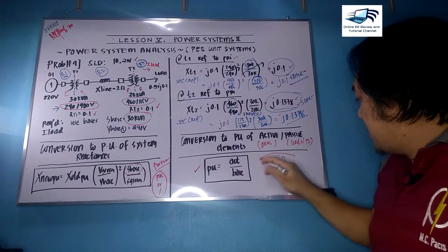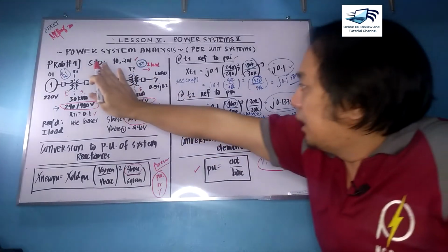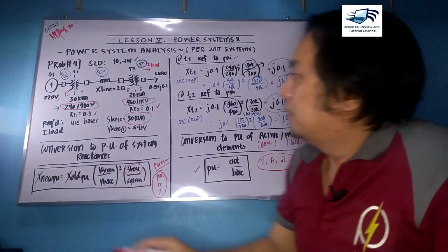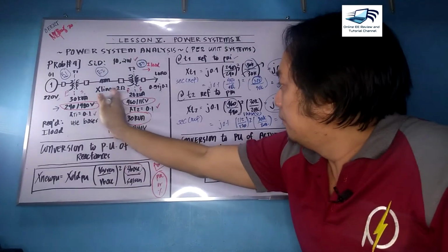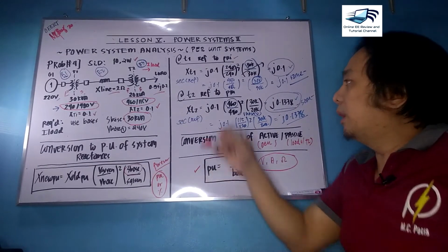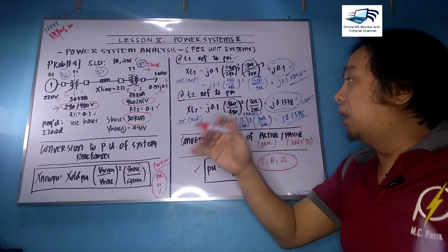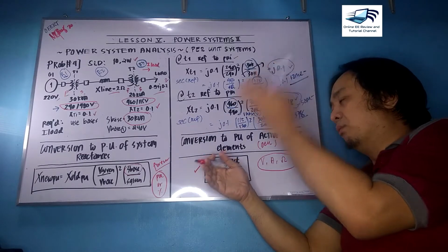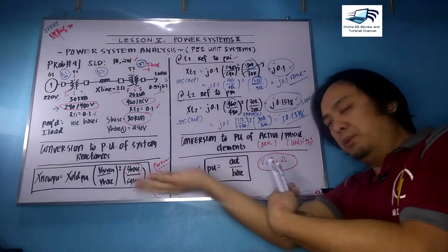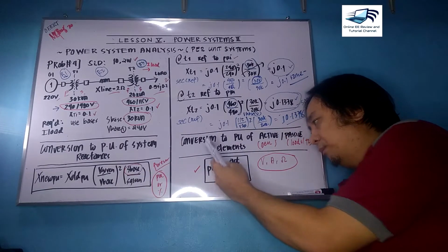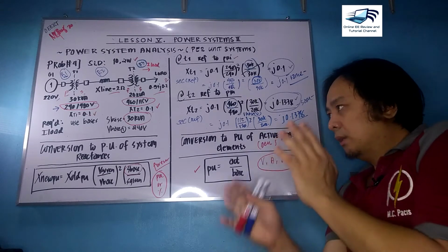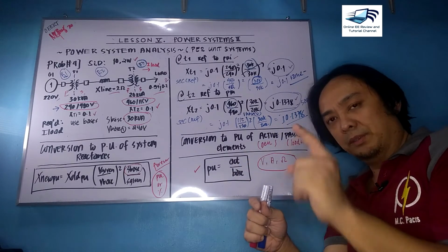If you have these values that you see on your single line diagram, such as your generator 1, your transmission line, and this load, these obviously are in ohms and volts respectively. And if you divide them by the base computation from the previous slide, you can obtain a per unit value. So we will continue the conclusion of this problem on the next slide.